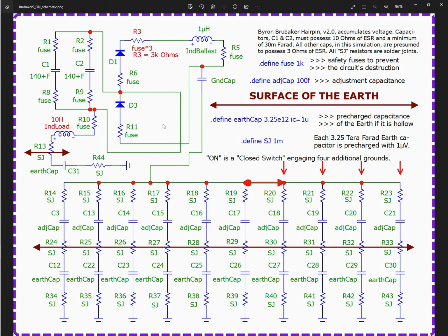And because diodes function similar to a switch, and a switch has both spark gap and capacitive characteristics to its behavior as you open and close the switch, the contacts move close together. That's a parametric variation of capacitance. They move apart. That's another parametric variation of capacitance. And if they get close enough, you'll get some sparking. You won't see it, most likely, but it's there.